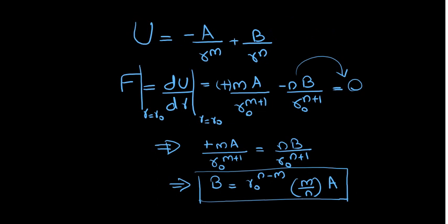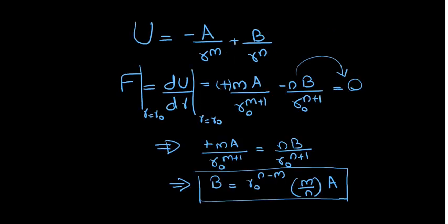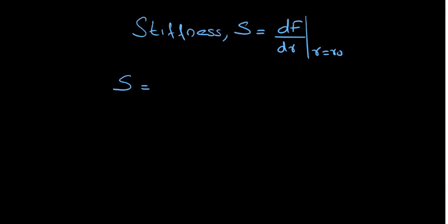So if I differentiate this force again with respect to distance, S is equal to, differentiating this equation, minus of m into m plus 1 a by r0 power m plus 2, since stiffness is at r equal to r0.